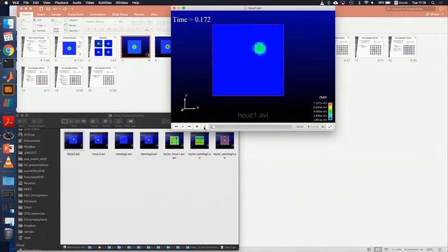Here you see our blob almost immediately disappears completely. That looks like physical diffusion, but it's numerical. It should not exist. And again, we will see later on how exactly our truncation error relates to this diffusion. So that's one scheme, called upwind 1, a first order scheme.